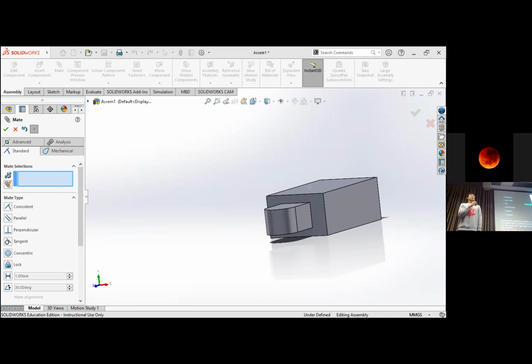For layer height, it's a bit like resolution. Higher layer height will print faster, and lower layer heights will be more detailed. Infill and wall thickness will directly correlate to strength. If you want a stronger print, it's often better to increase the wall thickness first than to increase the infill, because it's like a pipe. Most of our strength will be on the outside of the pipe.